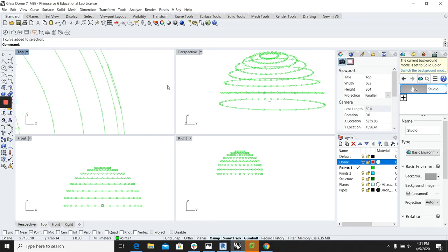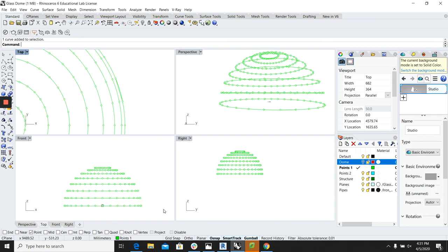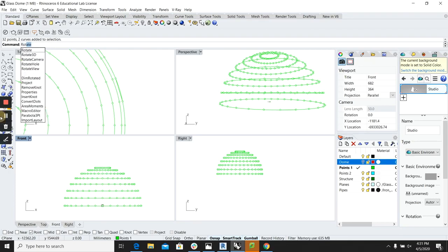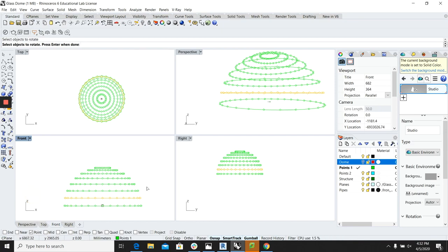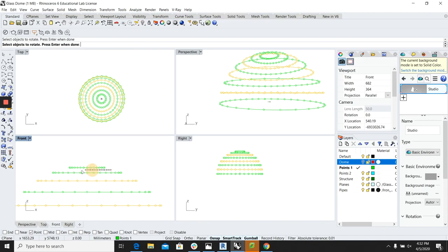So here's our line, and basically this line is going to create a reference point that we're going to rotate from. So let's just go to rotate again. So let's rotate and select every other point. And press enter and make sure you have copy on no.